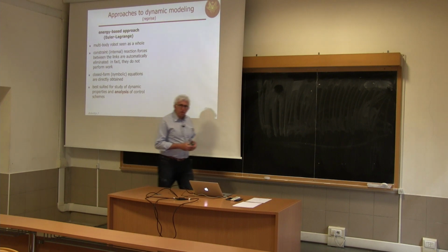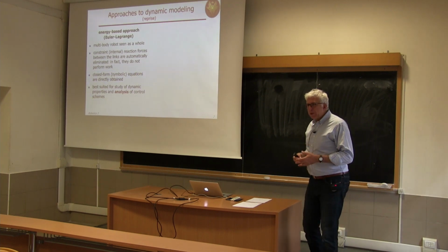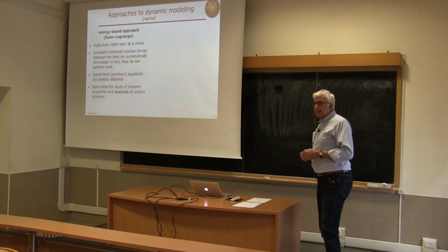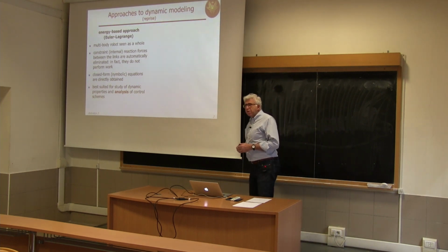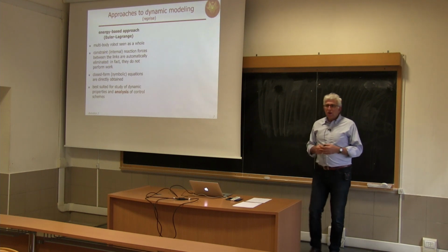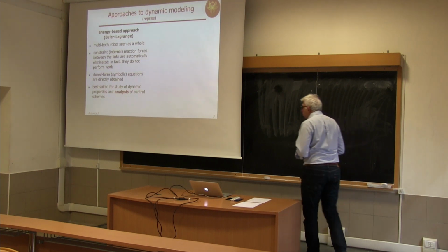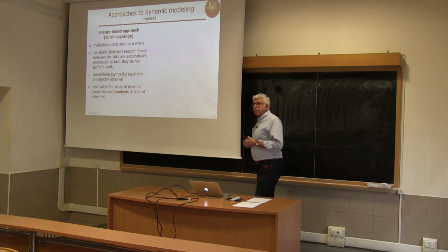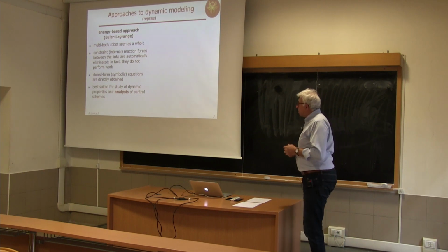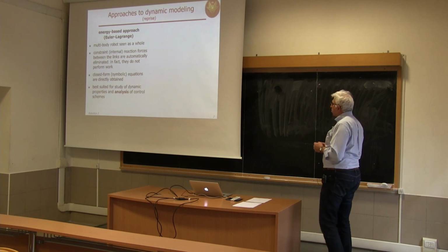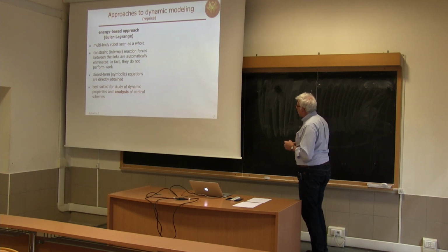There is no information at all on the forces exchanged between bodies while moving or while standing in a static situation. Because these internal forces are never generated, because, remember, on the right-hand side of the equation, we put forces only performing work on the generalized coordinates. So since the internal constraint forces which connect one body to the next one through the joints are never produced, they are eliminated from the picture. This is important for what we will see next on the Newton-Euler method.